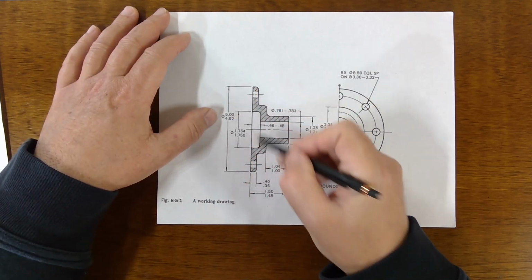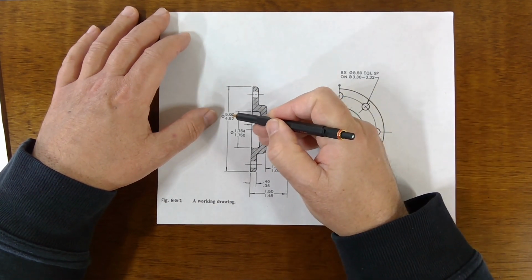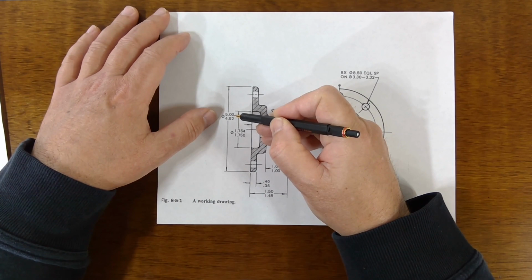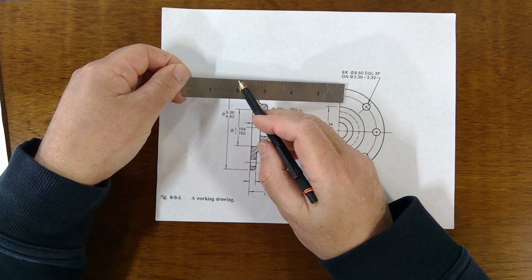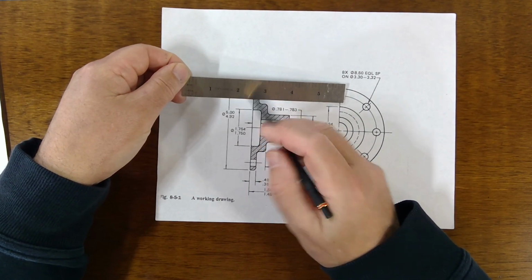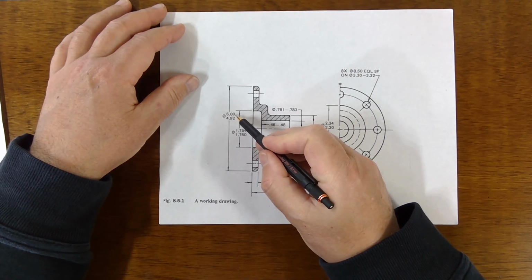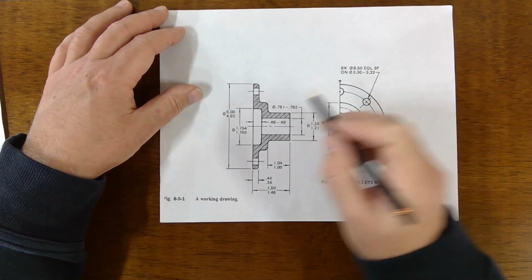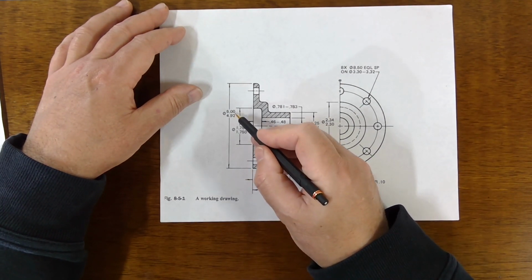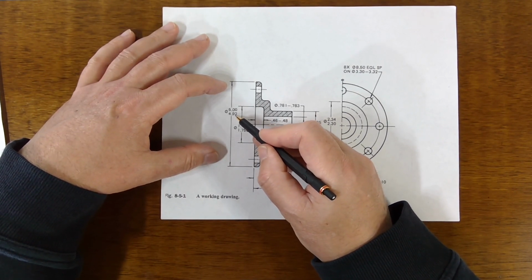So they're assuming that the person manufacturing this, or the machine manufacturing this, can hold an accuracy of at least 2 decimals. Like this little ruler right here, it's accurate on the top to 1/8 inch. It's accurate on the bottom to 1/16 of an inch. So this thing here, they're saying it's accurate to 0.00x. It's to at least 2 decimal points. Okay, so you can specify this. It looks like a fraction, but it's not. It's a range, right? So the biggest value is 5 and the smallest value is 4.92.